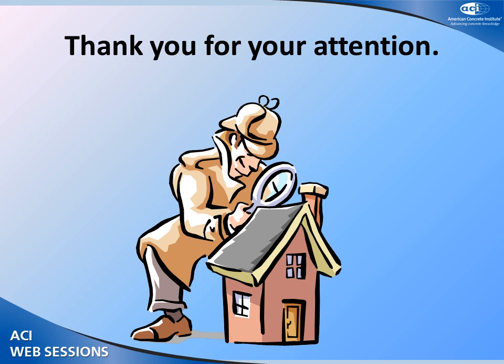Right, that's a very good point. In fact, I'm missing the ACI 211 meeting, mixture proportioning right now. We spent a whole meeting one time discussing that very thing. If you've got lower moisture contents, 3 or 4%, then you're only talking per cubic yard, maybe a pound difference or so. But once you start talking 8 or 9%, especially with materials with high absorptions, then it's the high absorption that is really going to get you on the difference of that. Then you can start talking 5 pounds or more, which can dramatically affect your water cement ratio or your slump.